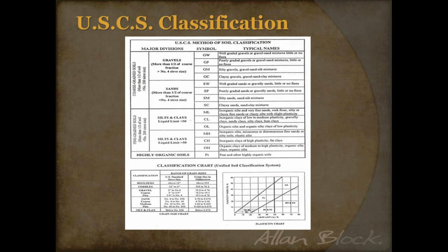But then you get down into your clays, and you'll see with clays that Atterberg limit, that liquid limit, really comes into play here a little bit. And so if you got ones that are lean, that's where the L comes into play. If you got ones with the H's, that's that heavy clay. Those are the ones that are being classified by the higher values there. Right? So just keep that in mind. Like I said, there are many different classification systems out there, but they're all rooted in the same option here.